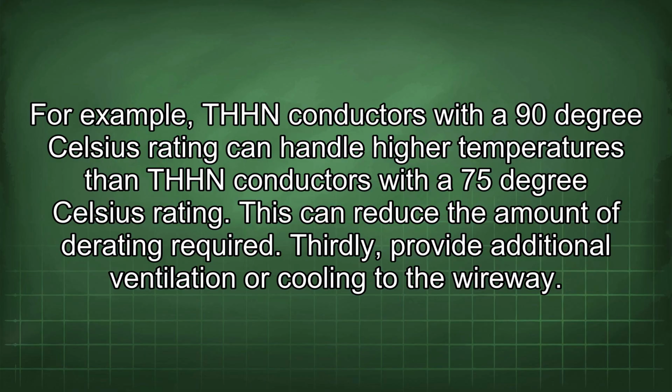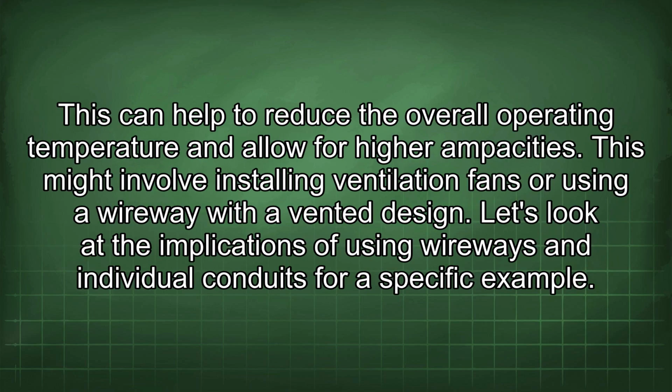Thirdly, provide additional ventilation or cooling to the wireway. This can help to reduce the overall operating temperature and allow for higher ampacities. This might involve installing ventilation fans or using a wireway with a vented design.